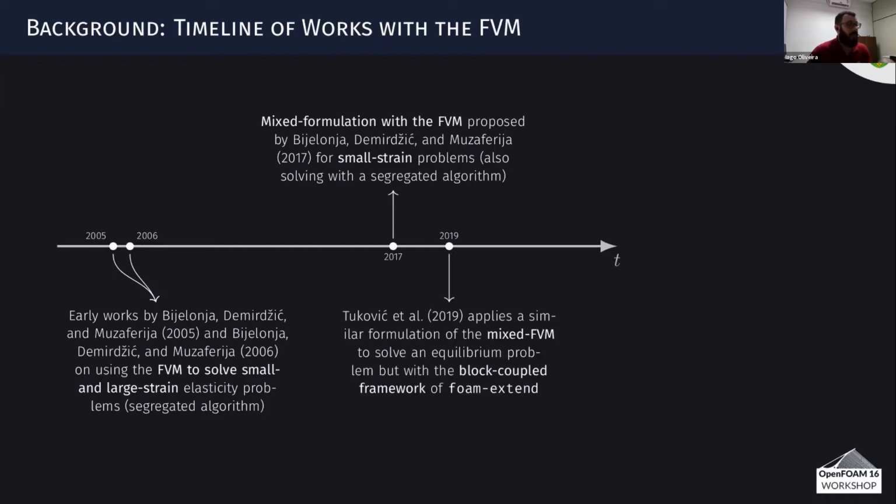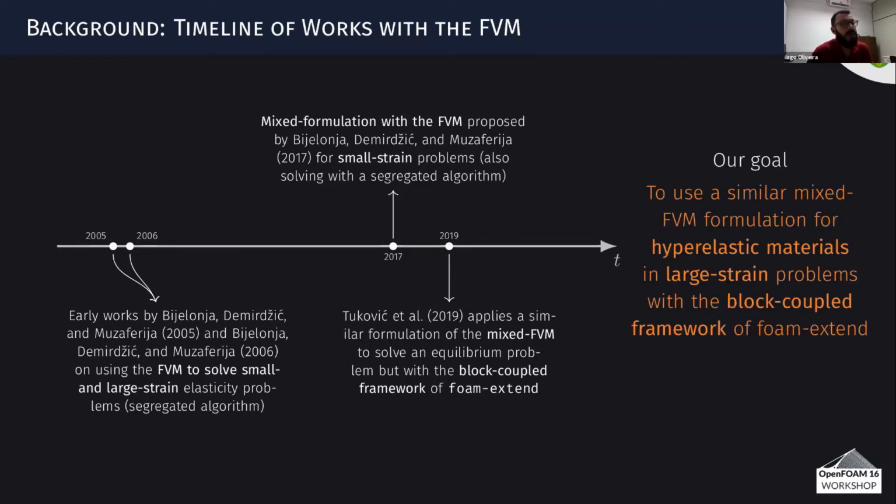More recently, in a presentation at the same workshop in 2019, the same methodology was implemented with the block-coupled framework of foam-extend, but for small strain problems. This brings us to our goal, which is to use a similar mixed finite volume method with the block-coupled framework in foam-extend, but to solve large strain problems of hyperelastic materials, thinking mainly of solving the intracranial aneurysm motion, specifically.